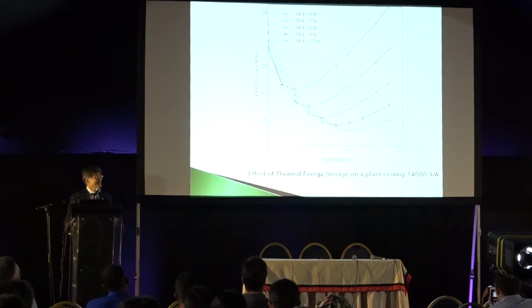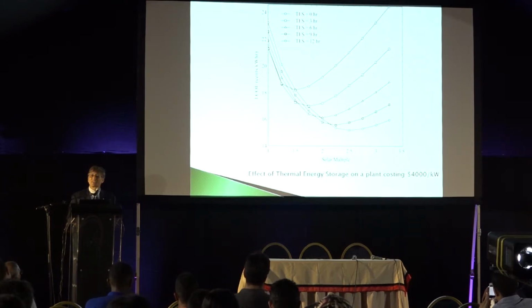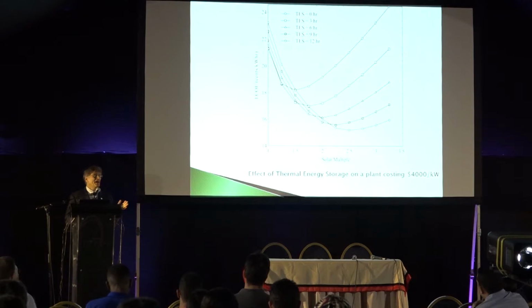However, even though capital cost of storage is being added, the levelized cost of energy is actually going down. That is because with the thermal energy storage, the investment that you made, that you otherwise were only using during the daytime, now you can use during nighttime also with the energy storage.